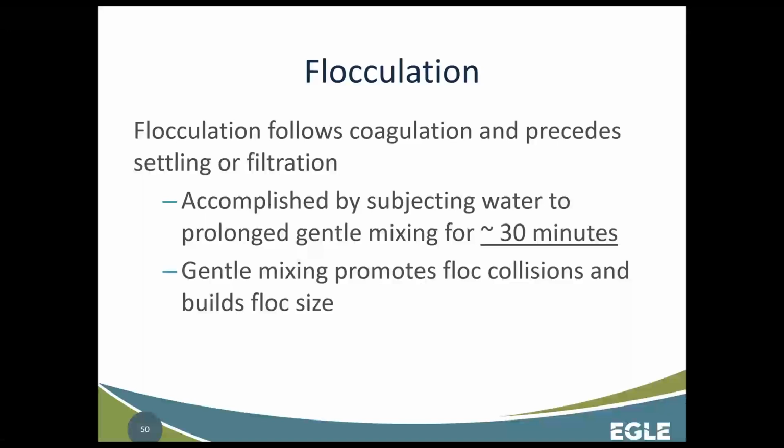Flocculation is accomplished by subjecting the water to prolonged gentle mixing for about 30 minutes. With coagulation, we're talking about extremely high energy, really fast rapid mix, lasts a second, lasts 30 seconds, just a very quick process. Then we follow that up with flocculation, much slower mixing energy, much longer detention times. This gentle mixing is just to get these neutralized particles to collide and start forming whatever our desirable floc is. If we're going for pin floc, sweep floc, or trying to get some bridging by adding a polymer, it depends on what our goal is.